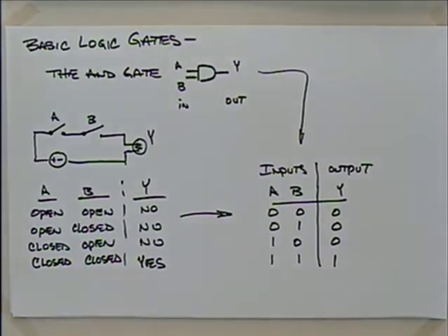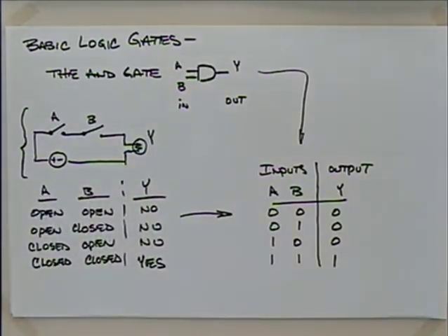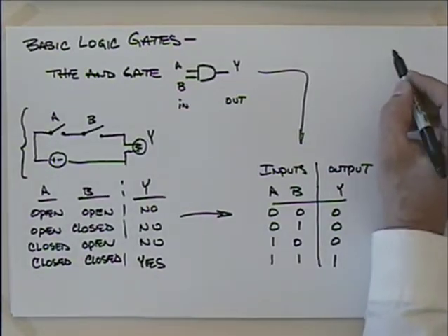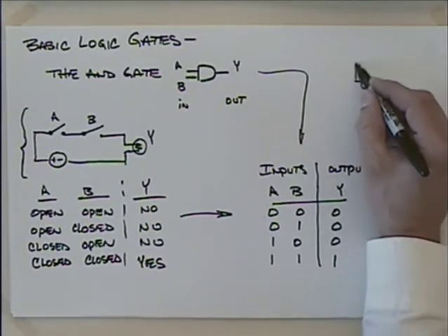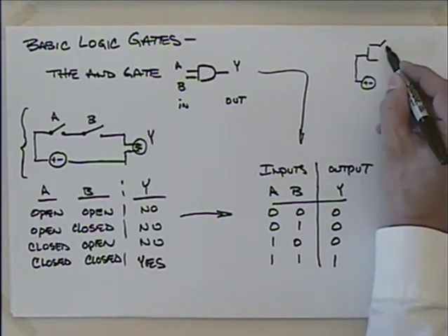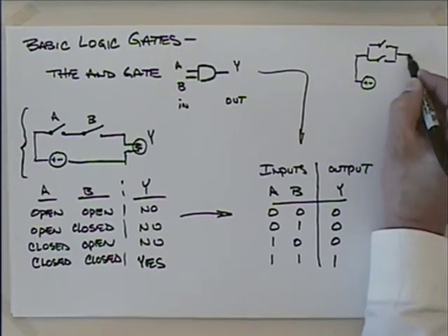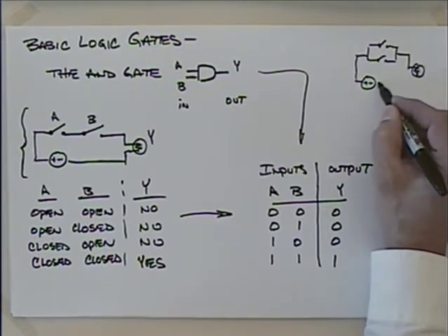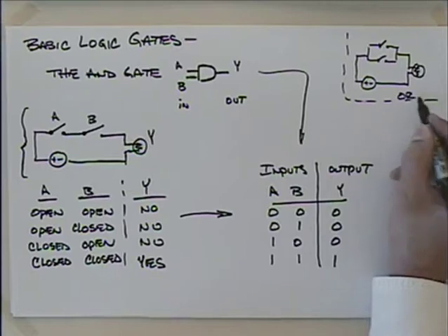So I mean, I could have said, well, you use this thing and you get that truth table. But I wanted to try and put this into a circuit that you could actually go down to the lab and build. Are there practical uses for a circuit like this? Yeah. I mean, when we compare it to the OR, I don't want to spoil too many surprises, but with an OR here, we're going to have something that looks like this. And it's going to have 2 switches that are in parallel rather than in series, running down to the light. Okay, let's keep this well segregated here. This is our OR.